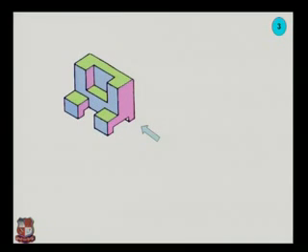Now we will consider the third example. Now as we can see in the figure, first of all, when we see the front view of this object, this is the pink color that is easily visible from the front view. Then, when we see further, as we see in the pictorial view, it is the gap, means there is no material in this portion. So when we see from the front view, this object is hidden, means it will come in the dotted line.